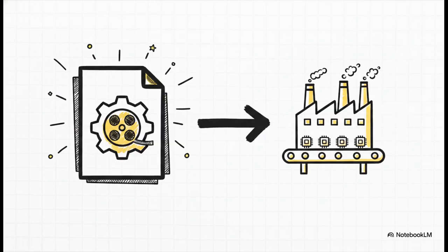And finally, Step 11, tape-out. This is basically celebration day for design engineers. Tape-out is where we take our fully verified, flawlessly timed counter design and generate the massive final manufacturing file, traditionally called the GDSII file. We send that file off to the semiconductor foundry. Our job in the design flow is officially done, and the actual physical manufacturing of the silicon chip can finally begin.